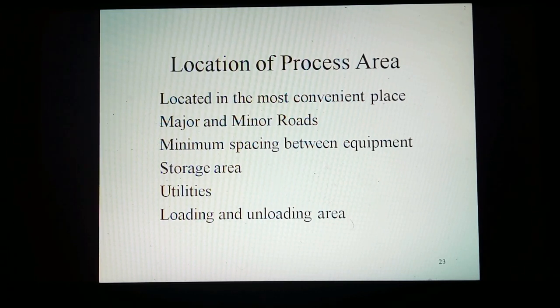The utilities area shall be located beside the process area for ready supply of utilities, except where they are an integral part of a process unit. Site utility units should be grouped together in an area classified as non-hazardous. Loading and unloading area shall be located on a corner of the site with capable connection to public road directly for inland traffics.